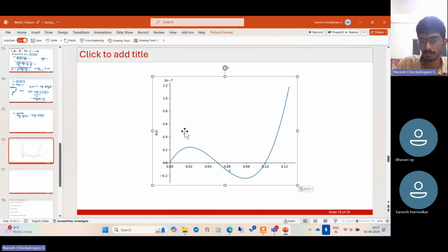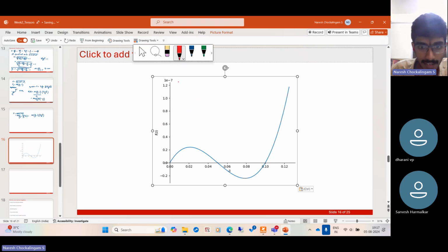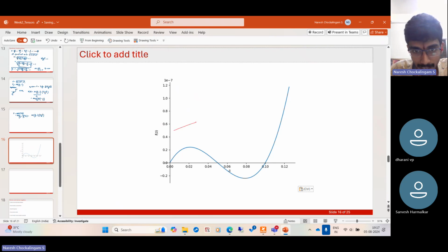Yeah. So what this physically signifies is, at this point, you have the truss like this. It starts deforming in the direction of application of force up to this point. Beyond this point, you cannot increase the force any further, because for the truss to be in equilibrium, you have to decrease the force. So with any further deflection, the force has to decrease. What it means is if you apply any more force, the truss will just accelerate. It will just jump from this point to this point, and further it will start increasing the load there. This process is called a snap through.